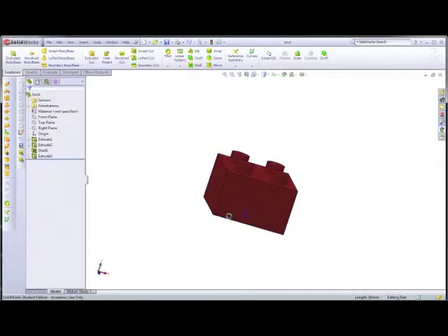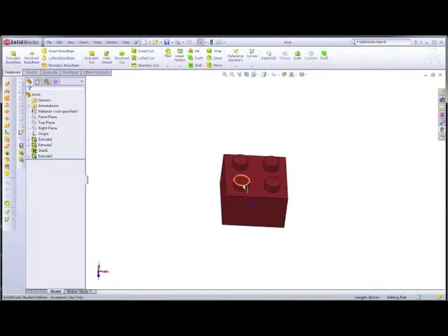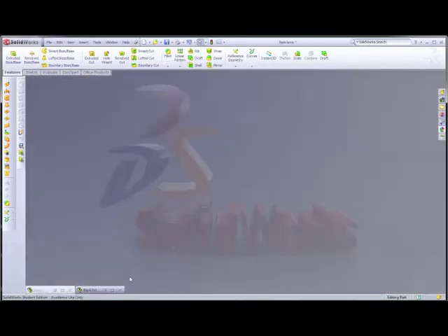Now if we go back into the brick that we created before, we can notice, oops, sorry, that's not the one. You'll notice that it's hollow, and we've also got these 4 sections on here. So first off, we're going to create these 4 circles on top of it here, and extrude upwards. So go back in, go back down to brick.